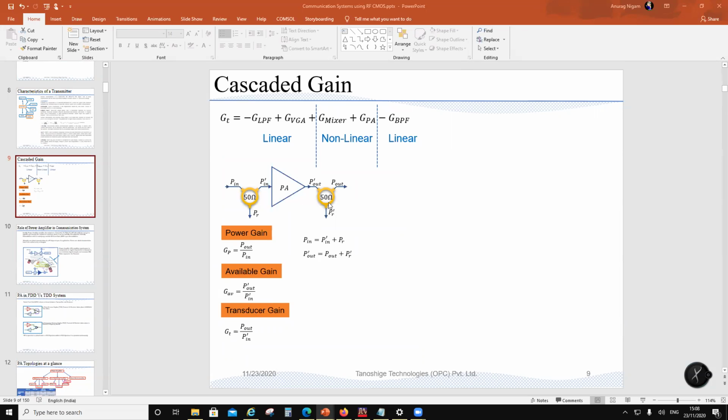Same thing is true for LNA. For example, if I tune the LNA for gain, then I'm looking at available gain or G max. Now, when I tune for noise figure for a LNA, then I would not have an available gain. It depends on where I'm allowed to put a mismatch, right? For example, for PA, I might tune the output for linearity or for efficiency, right?